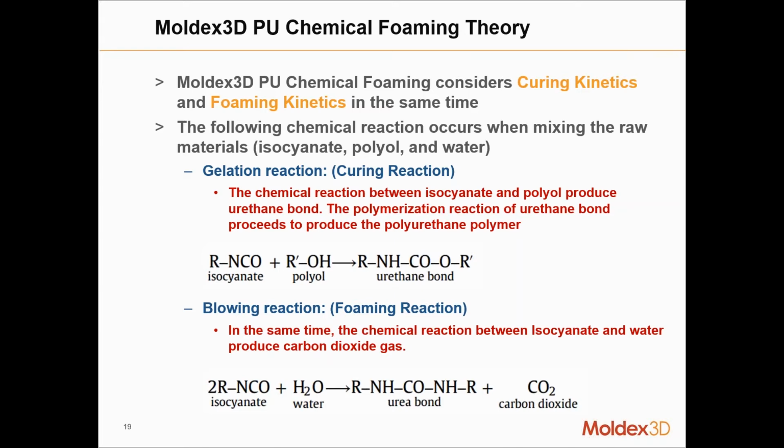And another thing that happens is, while it is foaming, it is also curing because it is a thermosetting material. So there are two types of kinetics that are going on at the same time. On the one side, the higher temperature causes the material to cure and solidify, while on the other side, the foaming occurs and tries to push the melt forward. So at some point, these could be opposing forces as well.